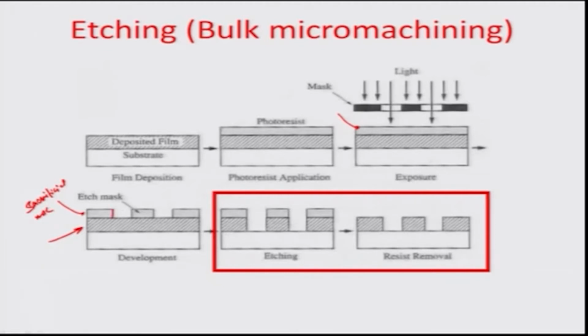So the sacrificial layer merely provides windows or regions across which such exposure can happen selectively. So the etchant can rush in through these windows and then affect the hatched layer, and you can see the hatched layer go away here, so that you are opening this hatched layer for further etching on this particular surface. So the idea is that you have a material which is acting as a hard mask, a material which is the soft mask that you have made for etching, and through the soft mask you are imprinting onto the hard mask and using the hard mask for doing further high aspect ratio etches into the final structure. So that is how you do bulk micro machining.